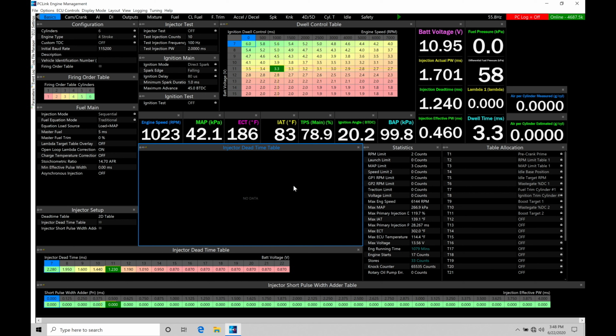Okay, so let's get started. We're going to be taking a look at working with our VTEC functionality and programming within our PC Link software. If we're trying to control a VTEC equipped engine, so a Honda engine that has the VTEC functionality, we need to be able to switch over from our low and high cam profile, command it from our Link software here. We're going to be turning on our VTEC solenoid when we like. Usually it's based on engine RPM at the very minimum.